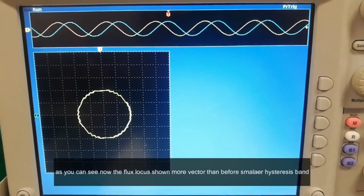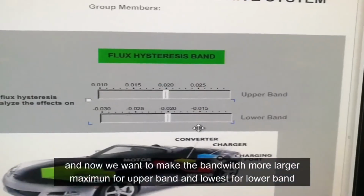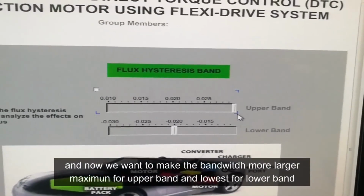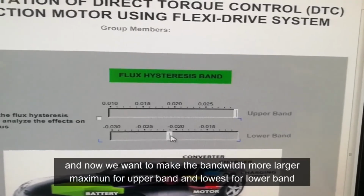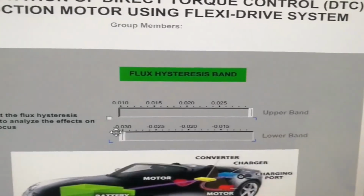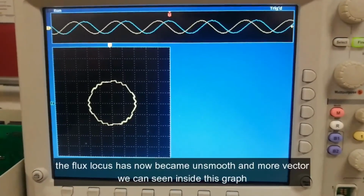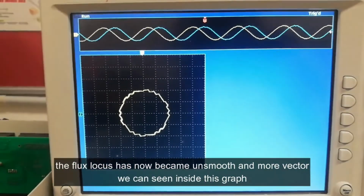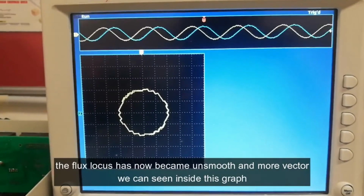Compared to the smallest hysteresis band, now we're going to make the bandwidth even larger by selecting the maximum for the upper band and the lowest for the lower band. Now the flux locus has become more unsmooth, and the vectors can be really seen inside this graph.